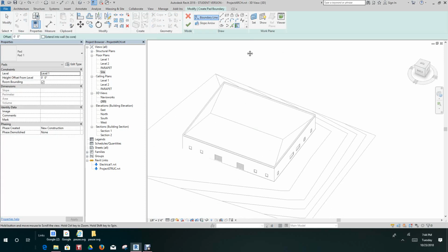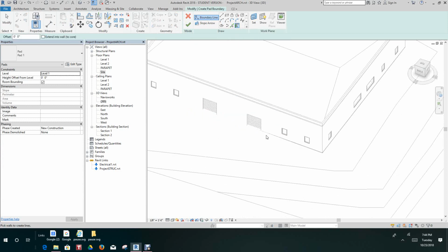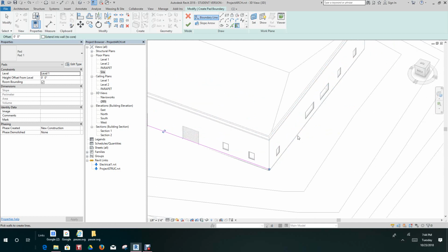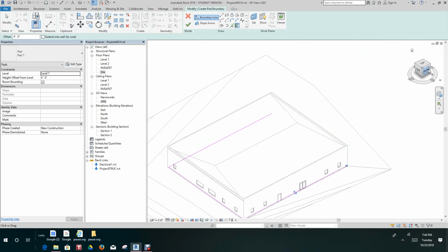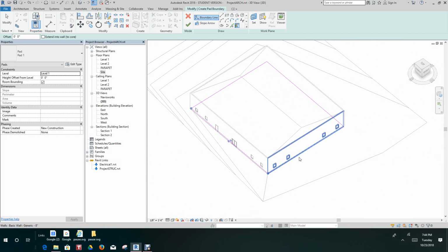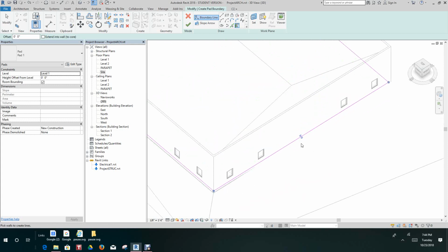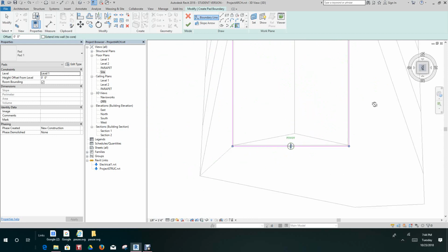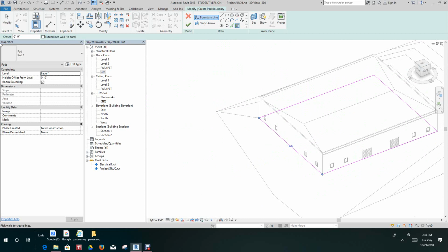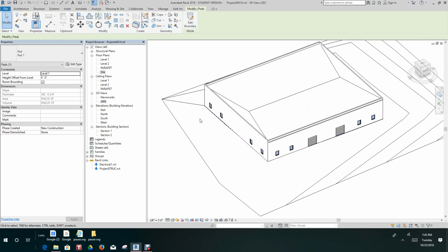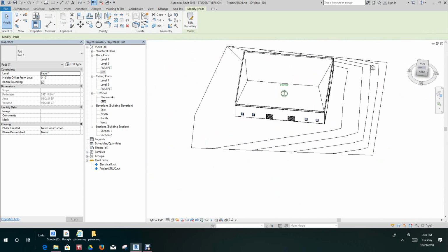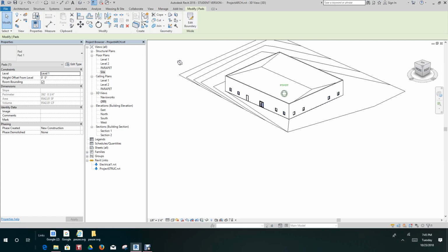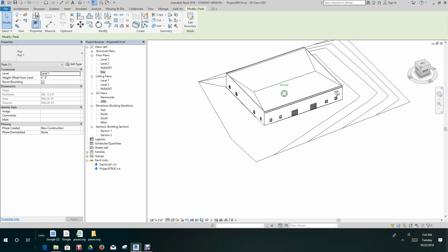And we want to do select walls, pick walls, and then we'll take this wall, this wall, this wall. Now once that's done, we want to set that on the outside. So now once that's done for our building pad, we'll just click the check mark, and there we got our building pad. So it sort of cuts right into the ground here. This is going pretty good. So there's our building pad, and we have our topo surface for our building.